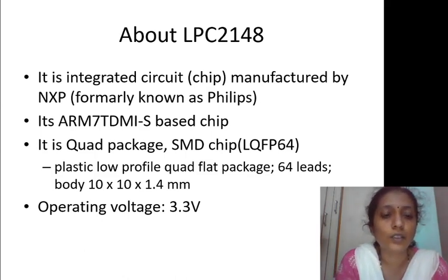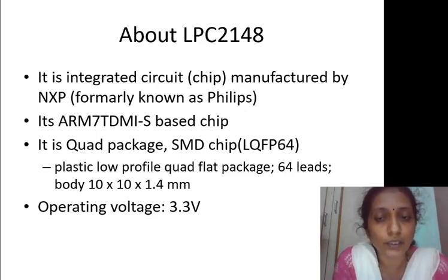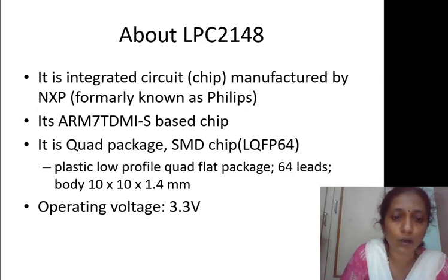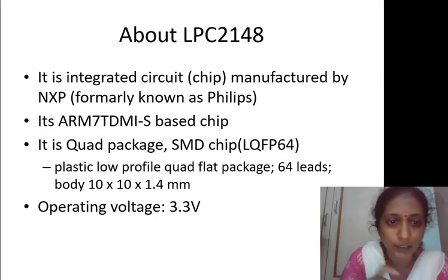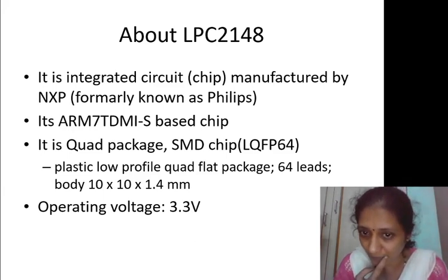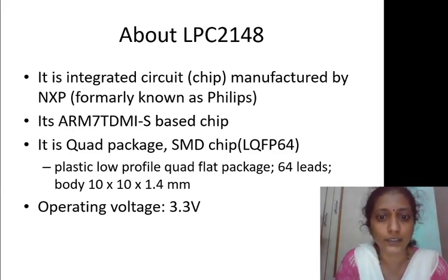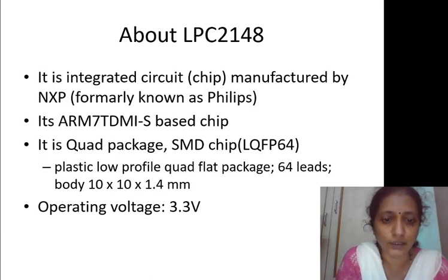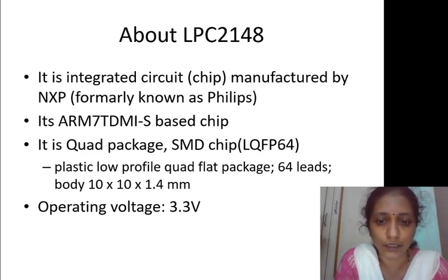So this is about the ARM7 TDMI-S architecture, which is supported by Lpc2148. It is a quad package, that is, it has 4 sides where the pins are available. It is a surface mounting device chip. Its package is LQFP64. It means it has 64 pins available. On every side it will have 16 pins.